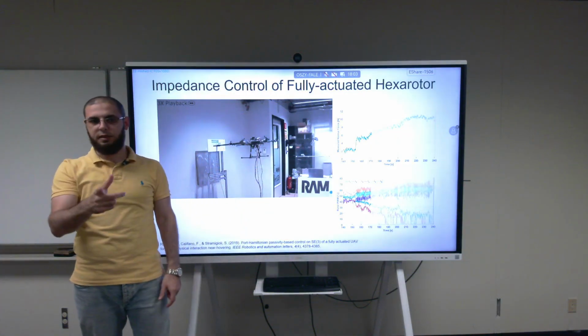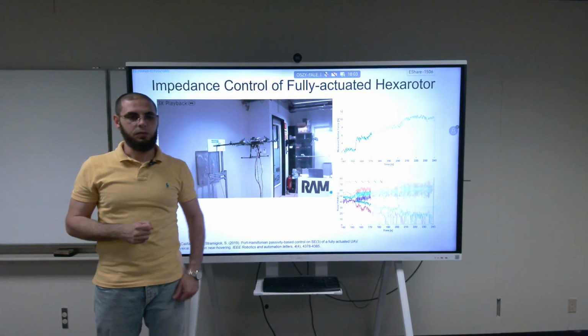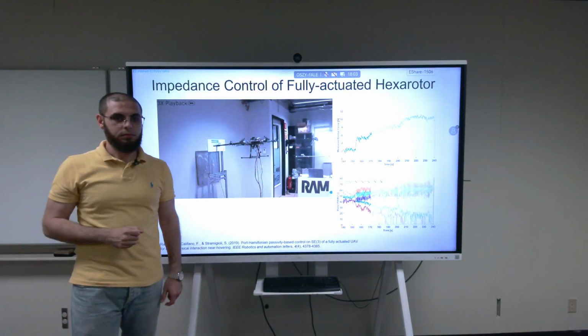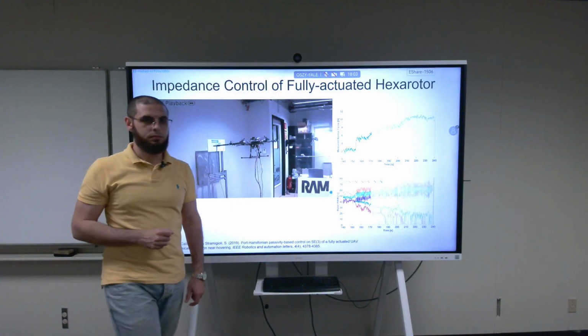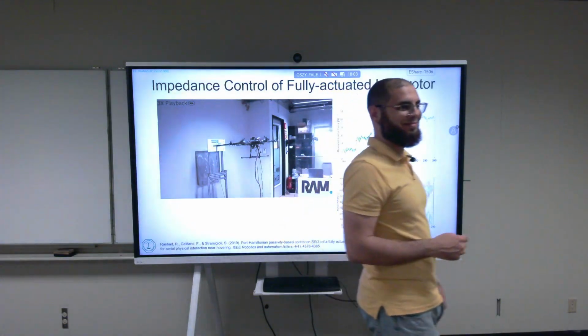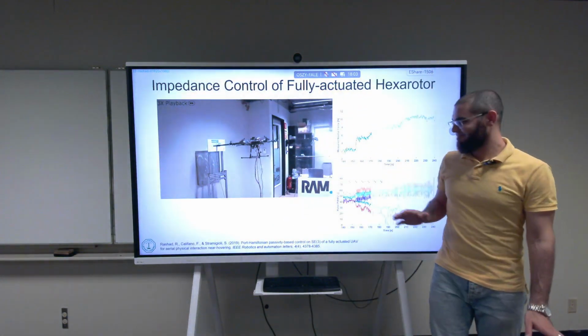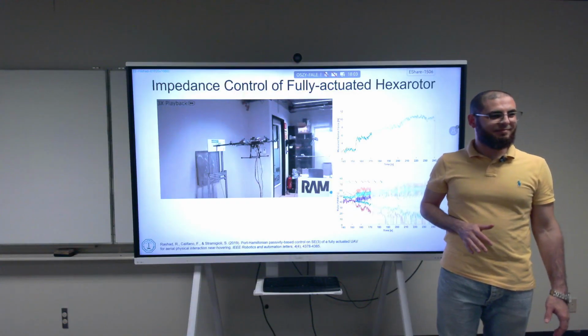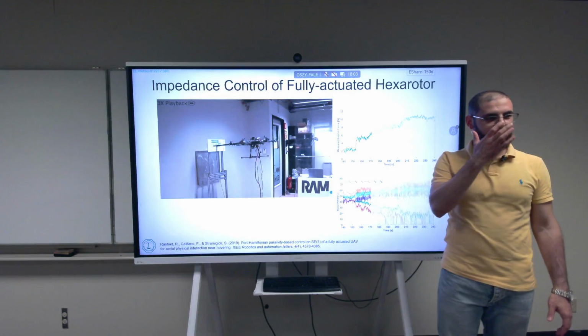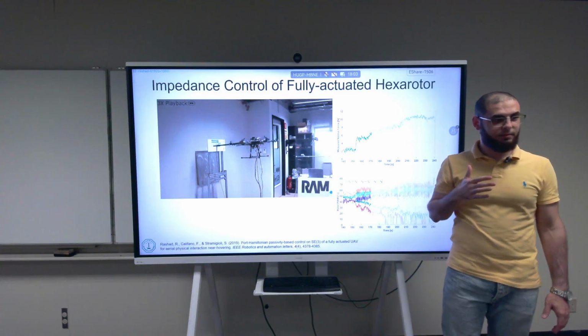When you're talking about impedance control with the drone, if you have any disturbances from the environment, the controller will not work for the body itself. So probably your impedance control is not on the drone itself. The drone itself will have stabilization control. Impedance should be just on the hand.